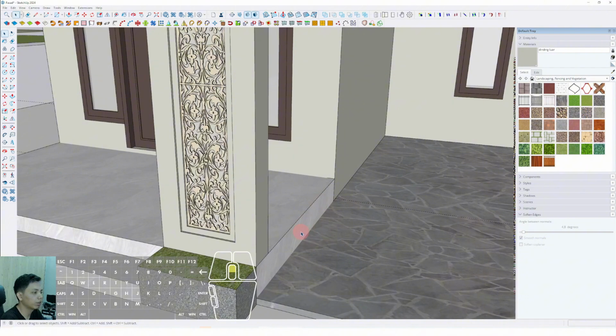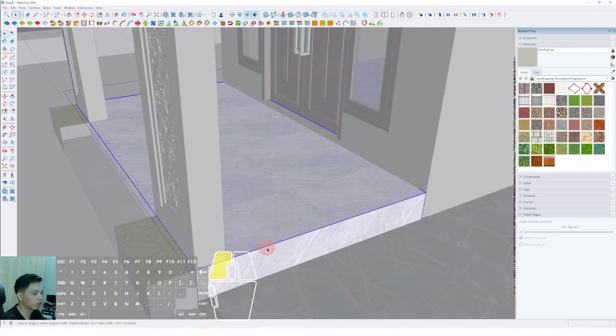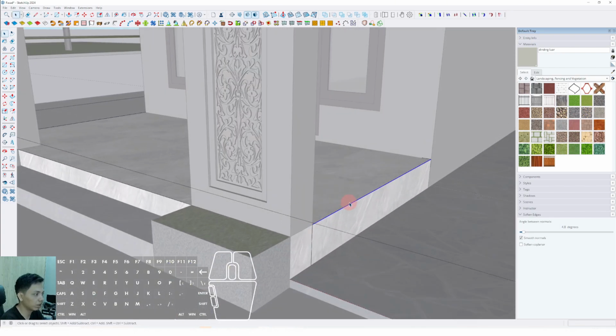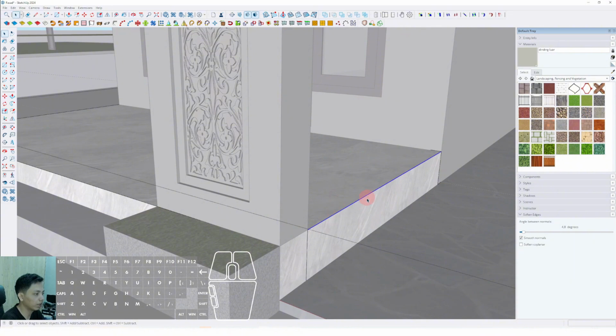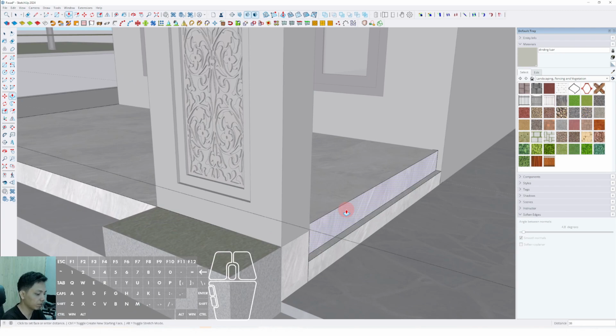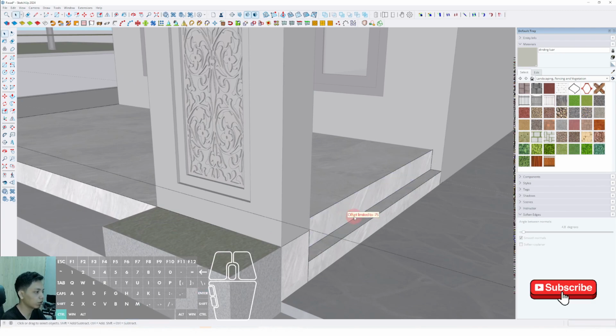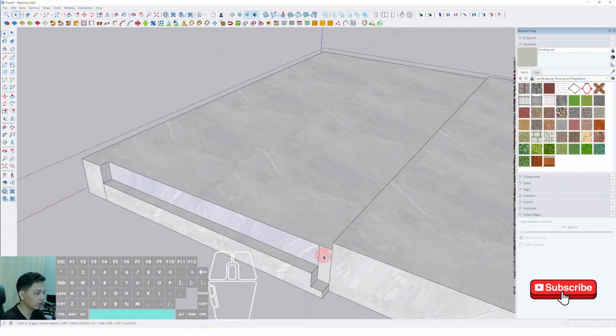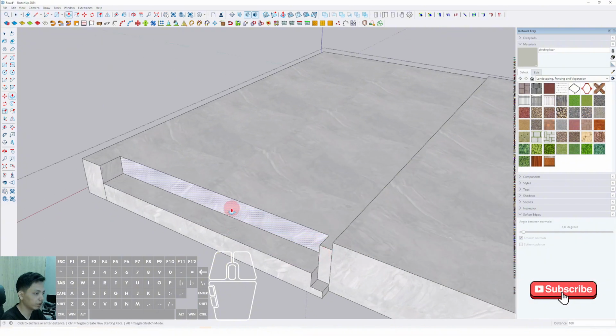Or you can also set the design, set the step, select the line, select move, press Ctrl, and then place on this position. Then we can push it to the behind around 300 millimeter. I'm sorry. We have to move it until 300 millimeter anyway.